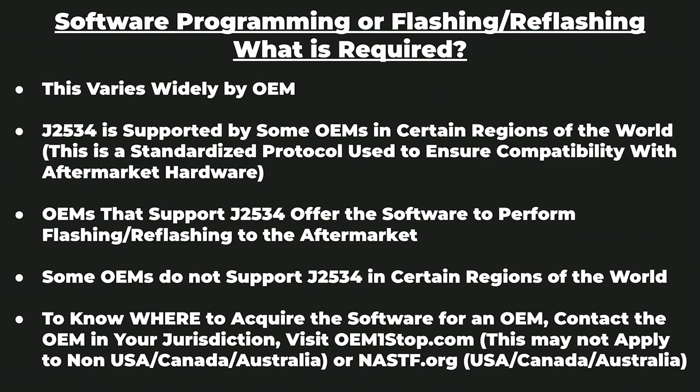Now, if you're not sure where to find the software to do J2534, in the US, Canada, and Australia, you can usually visit oemonestop.com. Also nastf.org. On these websites, you can find links to the vehicle manufacturer websites that then have information on where the J2534 supported programming applications live.